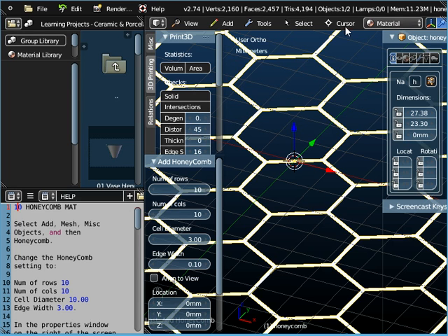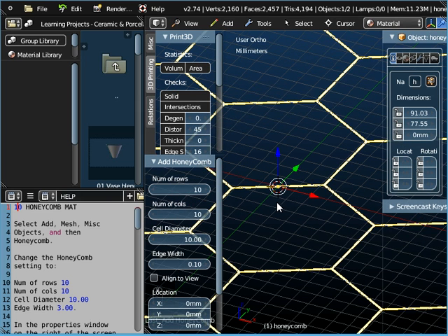3 millimeters across. Now I don't want to go using the interactive ruler at the moment. If I do that, this panel is going to disappear on me, so I'm trying to avoid doing that. So we've not got a perfect view of this size, but that's what the diameter is. Now we want to change this up to 10, so I'm going to enter in the value 10, and as you can see that makes it much bigger now. So there are actually 10 millimeters across there.